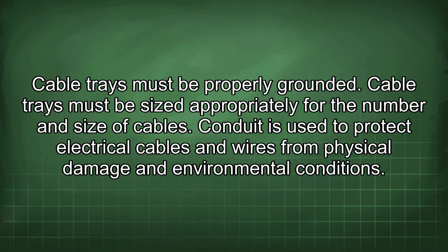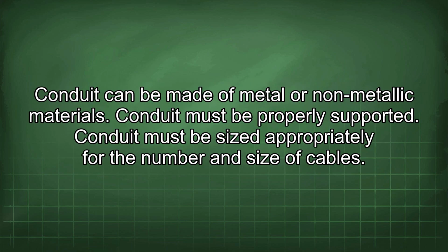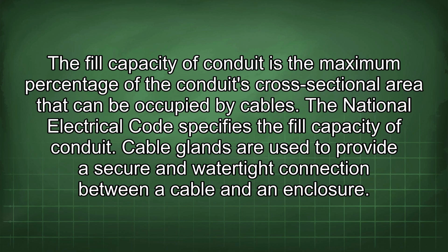Conduit is used to protect electrical cables and wires from physical damage and environmental conditions. Conduit can be made of metal or non-metallic materials. Conduit must be properly supported. Conduit must be sized appropriately for the number and size of cables. The fill capacity of conduit is the maximum percentage of the conduit's cross-sectional area that can be occupied by cables. The National Electrical Code specifies the fill capacity of conduit.